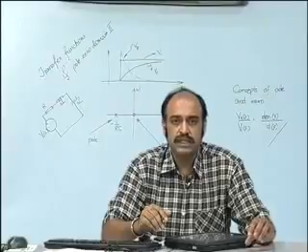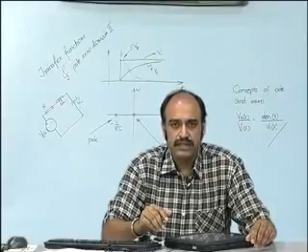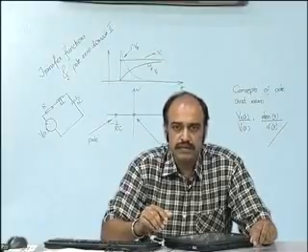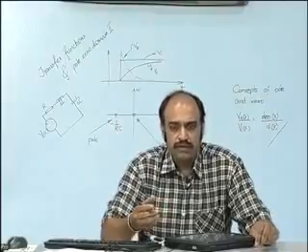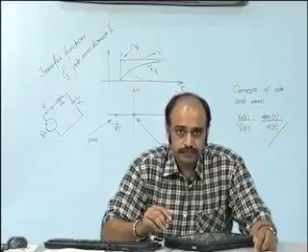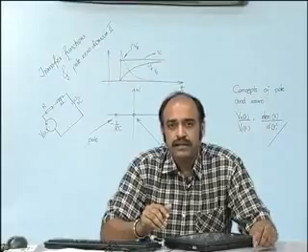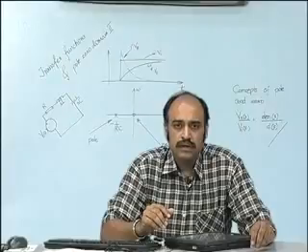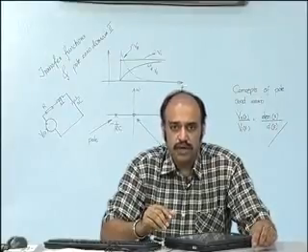Basically the transfer function is C (sI minus A) whole inverse into B plus D, that is, using the A, B, C, D matrices as the input matrices you can obtain the transfer function. We will see some of those examples in MATLAB today. Further, today we will try to consolidate the concept of pole-zero in the pole-zero domain using the transfer function model.